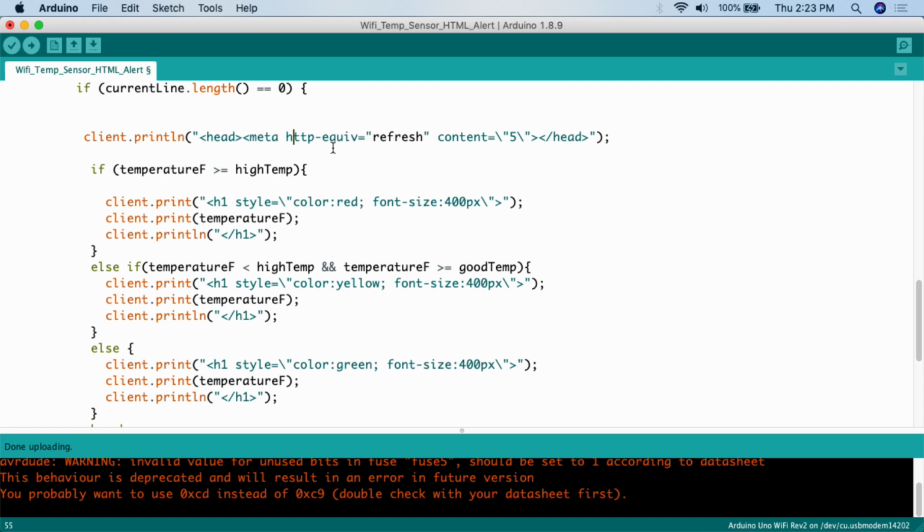But the problem is when you're writing this code, you have to be able to tell the Arduino what code the Arduino should care about and what code a web browser is going to care about, right? Since we print everything between the double quotation marks, if we don't escape out, and that's what a backslash is, essentially the Arduino is simply going to send everything between the double quotation marks.